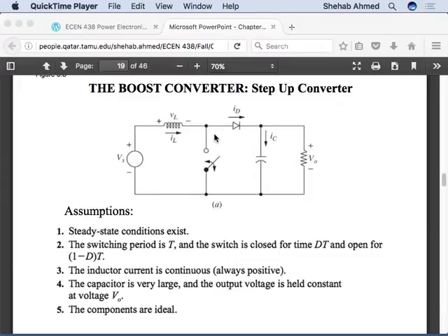So now we'll go to the analysis. Same thing: we'll look at the voltage across the inductor when the switch is open and when the switch is closed. We find delta I for switch open and switch closed. We know that we're operating in steady state, so any delta I up in the inductor will come down to the same value, so the sum of my delta I's will result in zero current change. Same analysis, and out of that we will come up with the voltage transfer ratio.